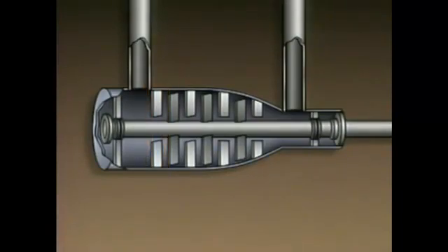During compressor operation, gas enters the suction line and passes by the inlet guide vanes. The gas then contacts the first set of rotating blades. The rotating blades accelerate the gas and push it toward the next set of stationary blades. As the gas is pushed through, a low pressure is created in the suction line. This low pressure draws more gas into the compressor. In some cases, these stationary blades can also be opened and closed to help control gas flow.